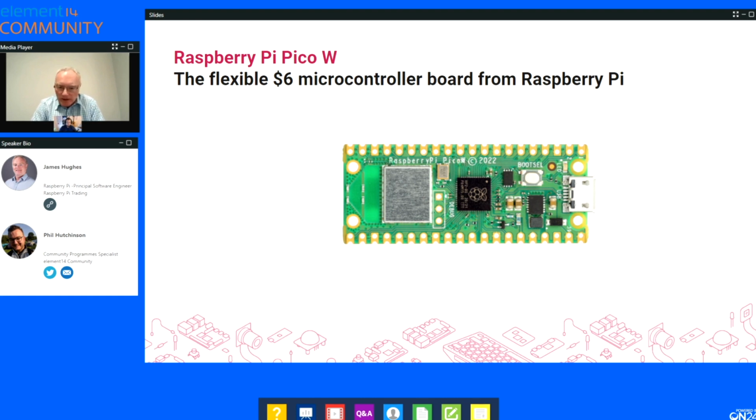And the important thing about this is that it's a modular approval. You can see that the device has a little can on it. I think that helps in getting this sort of approval. And it means that that approval goes into the product that you put the device into. So you don't have to then go through the quite difficult process of getting the device compliance that you need in order to sell into other markets.